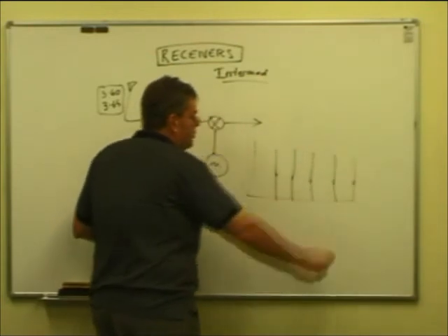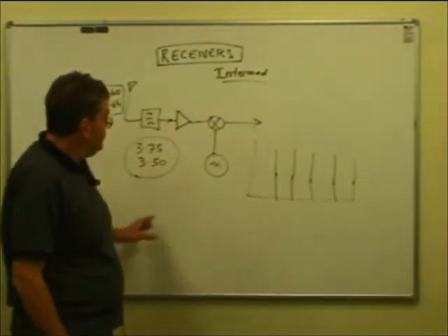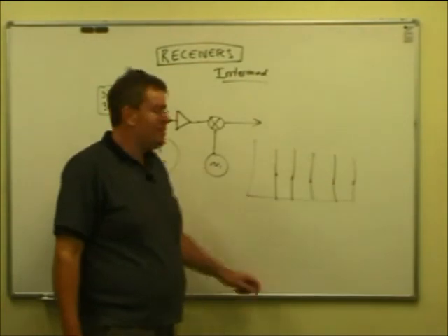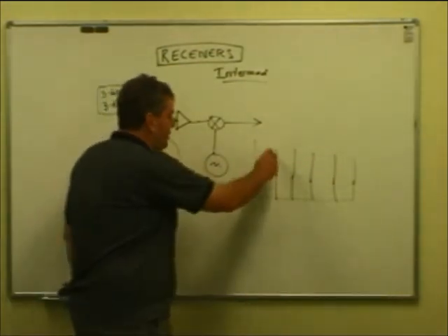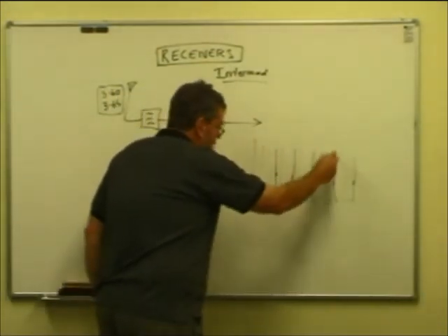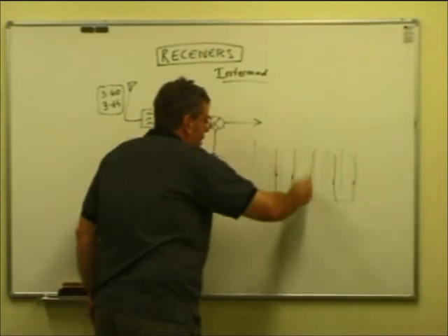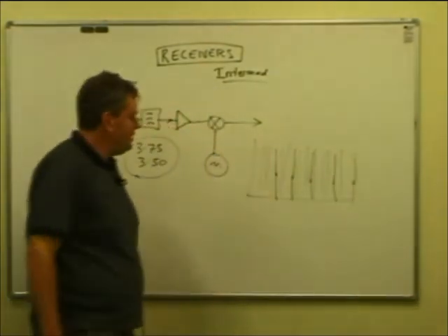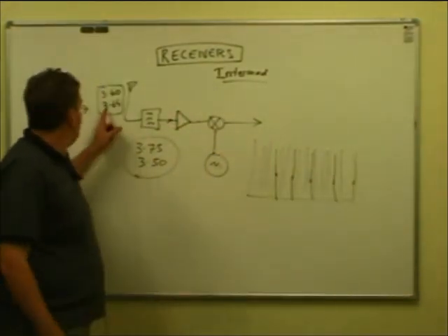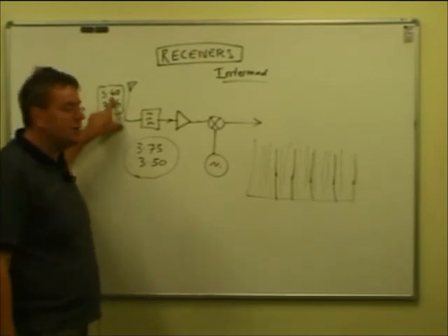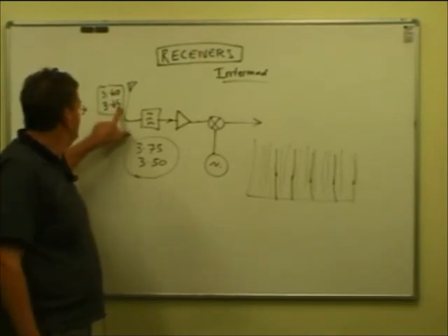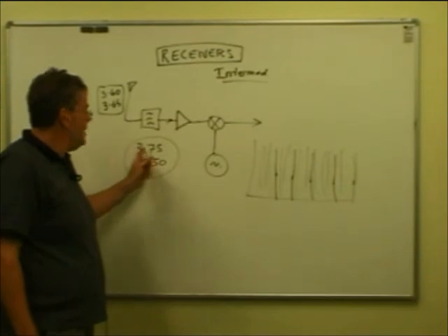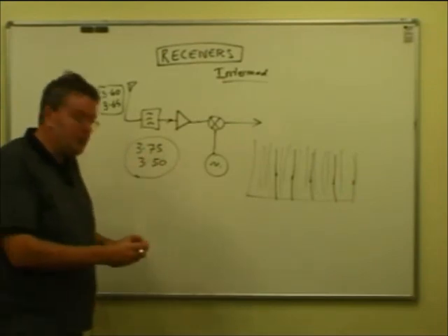If your front-end receiver is not very well designed, if you then do number analysis of all those signals, you suddenly get all these extra signals created. What happens is, say, in this example here, it's a conversation taking place at that frequency and another one at that, and what you'll end up with at these frequencies here sounds like an awful mess of the speech from those two.